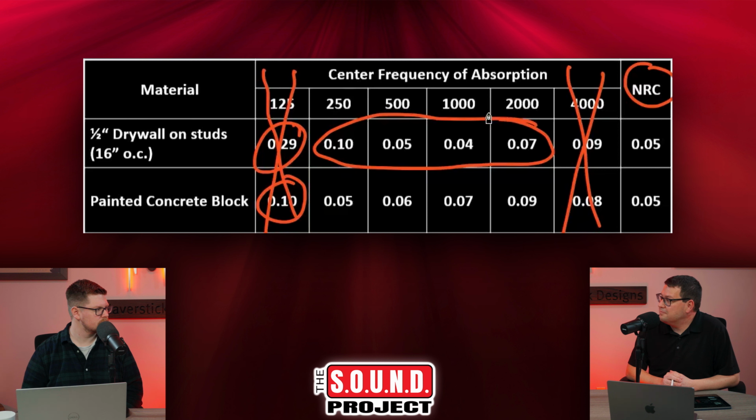and average them together. And that's why I rarely look at NRC, because if there is an NRC number, that means a test was done, because you have to have absorption coefficients to get to NRC. Sure. So I'd rather look at a test report and see how it does at all the frequencies rather than just the average there. Sure. And especially for what we do, it really is important to have it by frequency as opposed to just looking at an NRC.